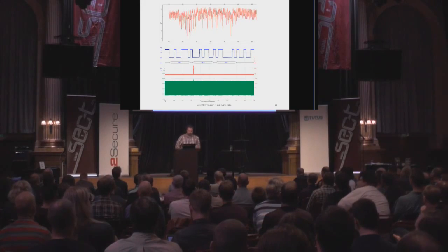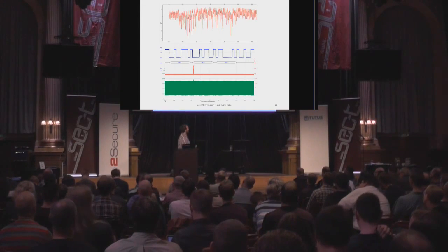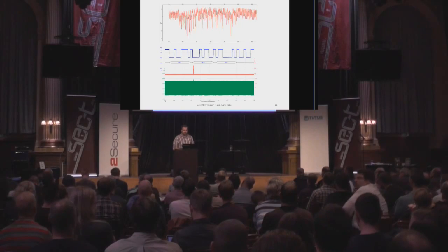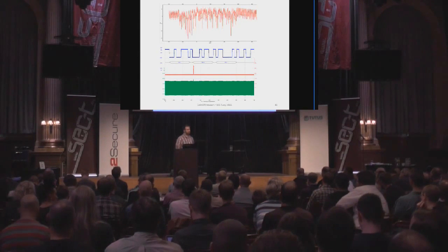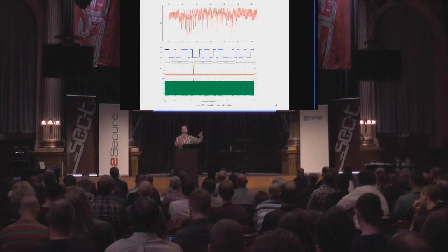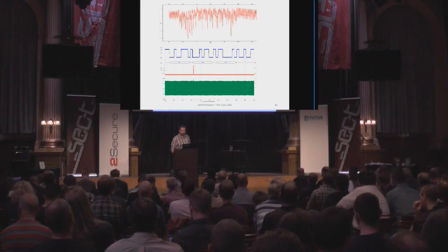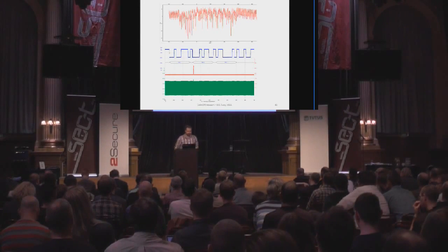All right, so the final thing people often ask about is, what about triggering? There's a few different ways. This is, how do I determine when to glitch or when to trigger my side channel measurements? The two most basic things I can show you are, one, the communications protocol. So here I'm triggering on data sent to the device. When I send it the authentication request, I can trigger on the bit pattern indicating that message is going over the wire and trigger the capture.